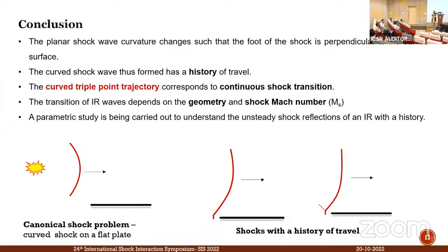Non-dimensional. Yes, non-dimensional. And another thing, Tara, I think we have to look into that. I think the Mach number is not supersonic. It's 0.9, for a 1.9 shock Mach number. I've actually calculated the flow, the F2 flow, and it is 0.9 only. I don't know how you are getting an expansion fan over there. So you have to look at that carefully.